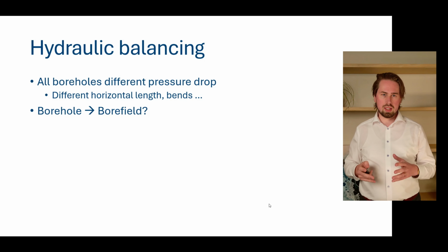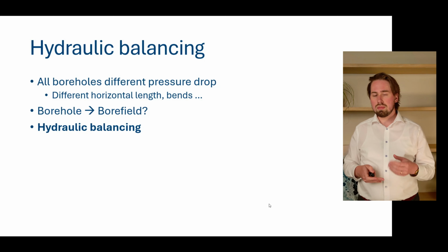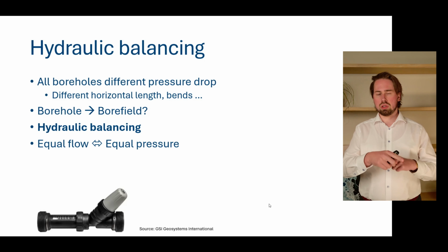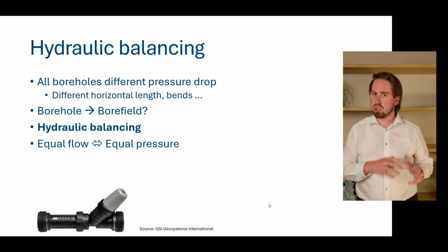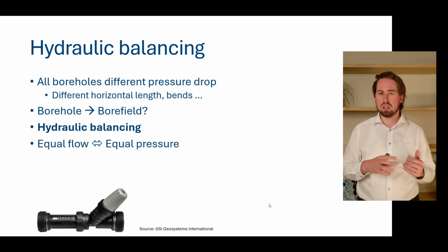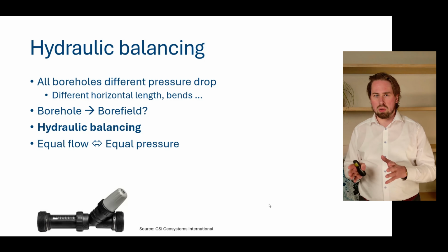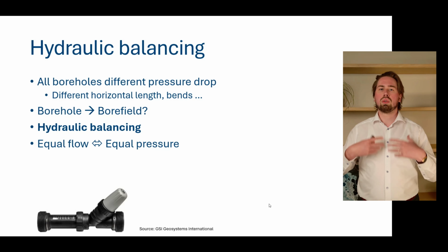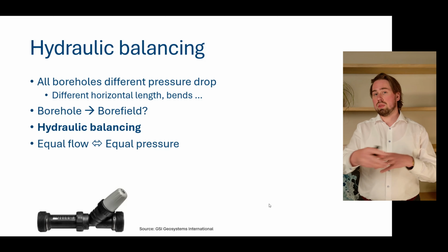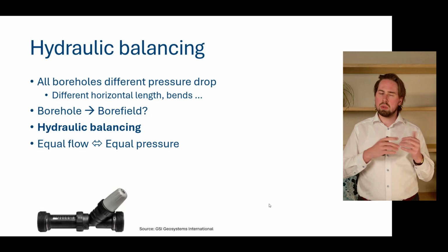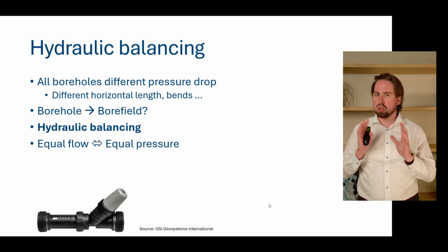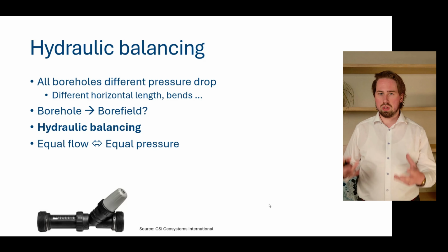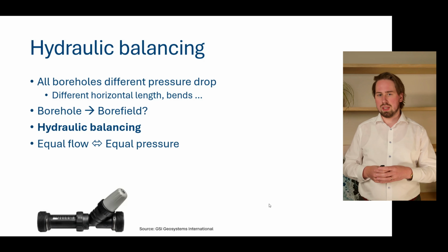This is done with the concept of hydraulic balancing. Now, what does this mean? It means that we want an equal flow through each of the boreholes. We already mentioned it when we were talking about parallel versus Tichelmann connections. We want this equal flow, because if we have an equal flow, each borehole has the same contribution to the energy exchange with the ground. Later we will see that that's not 100% the case, but conceptually, if we give them the same flow rate, they can have the same contribution to the thermal behavior of the system.